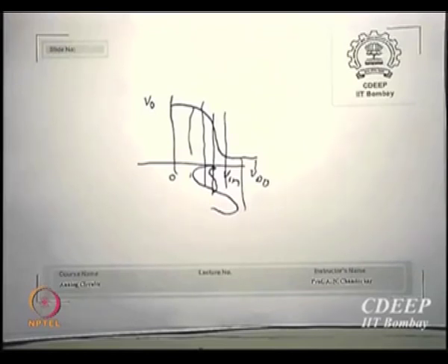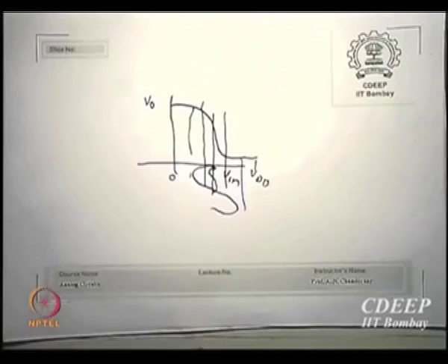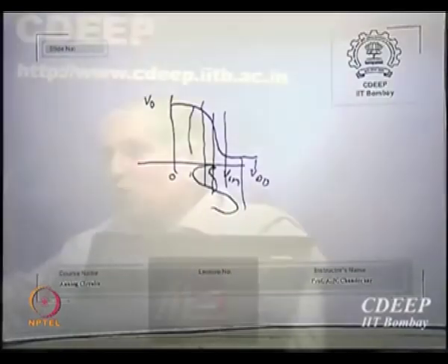Therefore analog circuits normally will have very small signal limitations, because if you go out, then what will happen? The power will go into other harmonics more than maybe the fundamental with the frequency, 2 omega t, 3 omega t, 4 omega, 5 omega. More nonlinearity, x square, x cube, x4, third, fourth, fifth harmonics will start appearing.